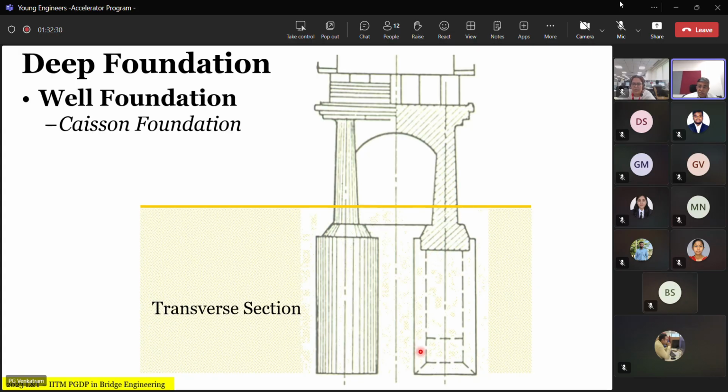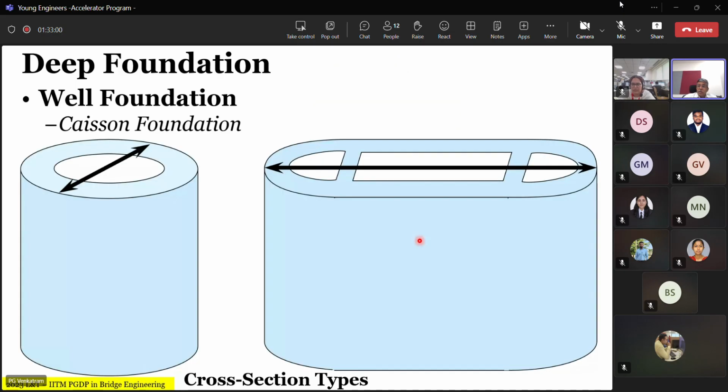And then when this 2.5 meters, that which was at this level, sinks down and comes to this, then they add another 2 meters of shuttering, cast that portion of the well steening, then grab further. The moment you grab further, the internal resistance of the soil is destroyed. So what happens is, under the weight of the steening, it sinks further. That way, progressively, you keep on casting and extending it. So construction of the steening is not a problem. But the process I have described to you introduces a certain complication in sinking.